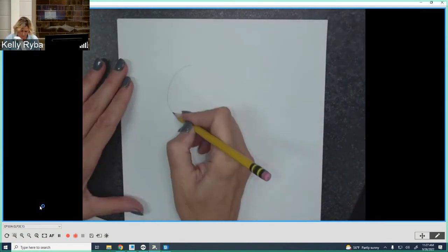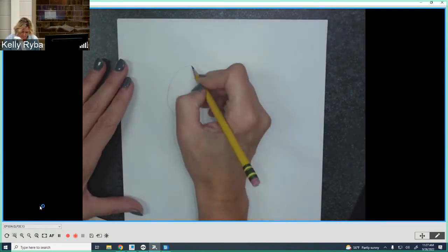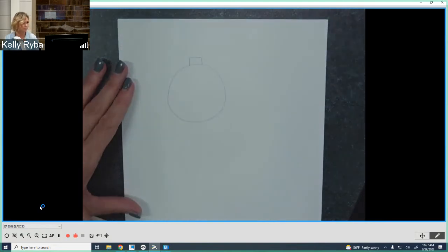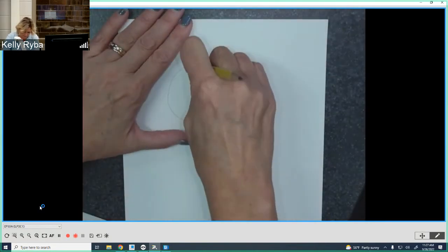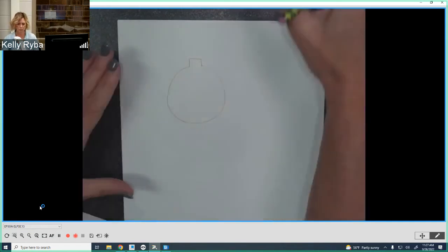Now, when we create a keyway, for instance, whether it's in CAD, AutoCAD, SolidWorks, Creo, we usually generate it from a surface, okay? That's like the top of the actual cylindrical feature itself. So if it's a hole or a bore, we'll do our hole, and we'll put our keyway, we'll generate it from the top here, we'll draw it, then we'll get rid of this portion that's right there, okay?